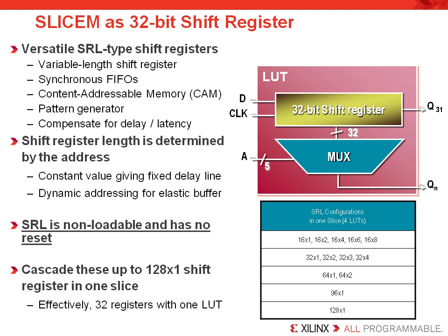The most challenging thing with this is that most customers don't realize that it is not loadable, has no reset, and only offers serial in, serial out capability. So if you try to infer it with any of these behaviors, your synthesis tool will instead infer regular registers, and that could be a big waste. The benefit of this resource is that it can effectively provide the work of 32 registers with a single LUT. In pipelined applications, that is a huge savings.